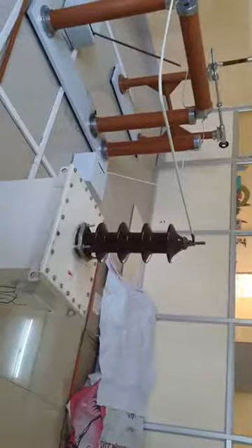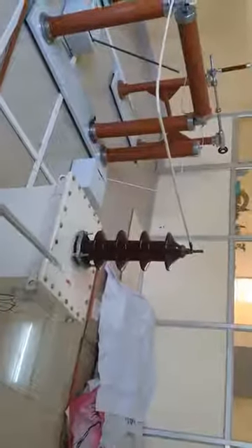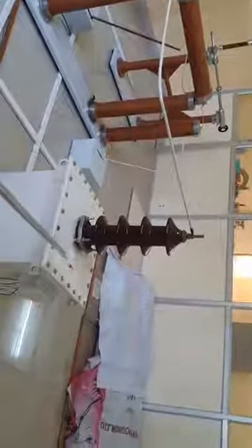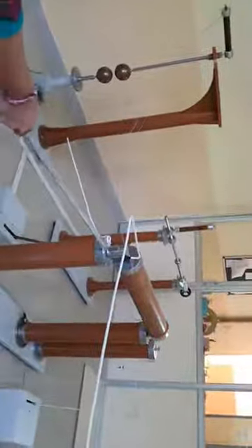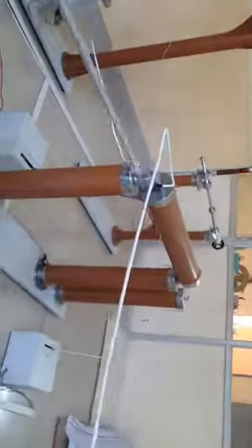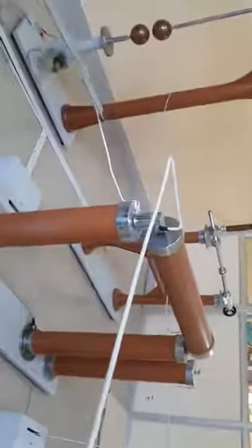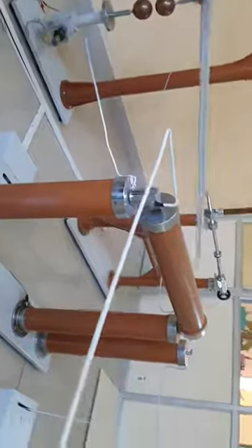After that we have a step up transformer. Here the 230 volts is stepped up to 50 kilovolts. Once it is stepped up here, that will go into the breakdown circuit connection. Here we are receiving the AC supply. This is the terminal for AC supply, and here we have a rectifier.